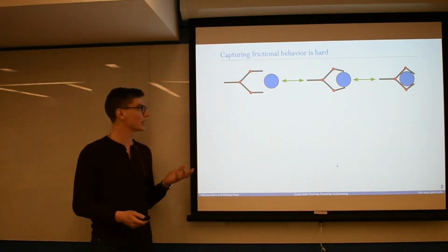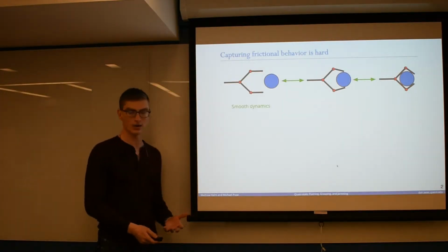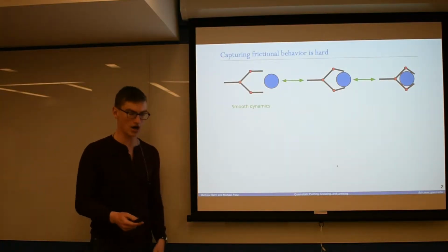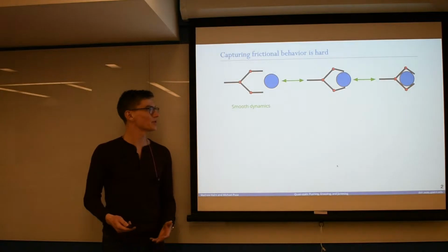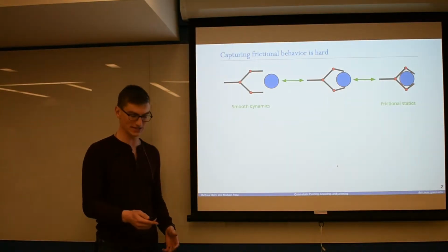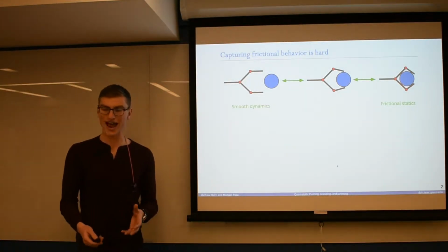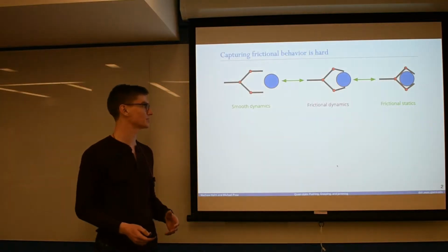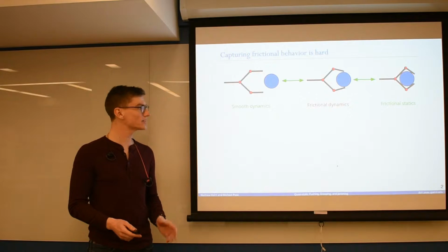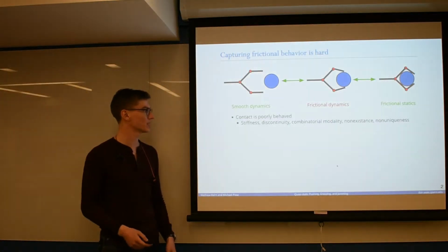So for a simple grasping task illustrated here, at the beginning, there's no contact between the object and the manipulator, and smooth Lagrangian dynamics are a very effective way of analyzing and controlling this system. Once a firm grasp is acquired, a little bit of additional complexity is added in analyzing the frictional statics of the grasp, but the acquisition of the grasp itself is actually far more complicated to analyze because analyzing it effectively means that you need to capture the dynamics of frictional contact.